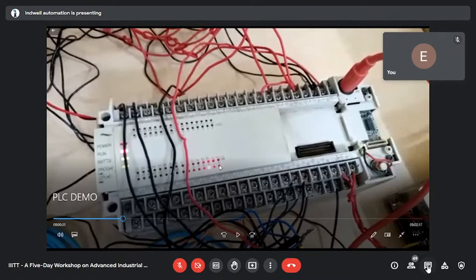And when you press this, if the indicator is not on, it means the PLC is not getting a signal from the input. Then if any output inside your program gets on, the respective output indicator will be on on your PLC. Then you can understand, okay, my output is on and the connected output should be on. So these indicators you will have, and these indicators are for run, for error, for stop, and other things.